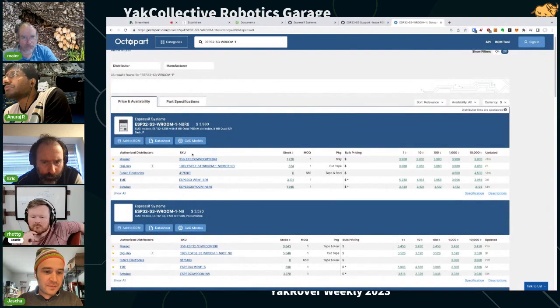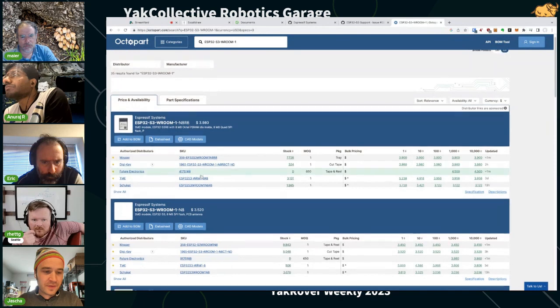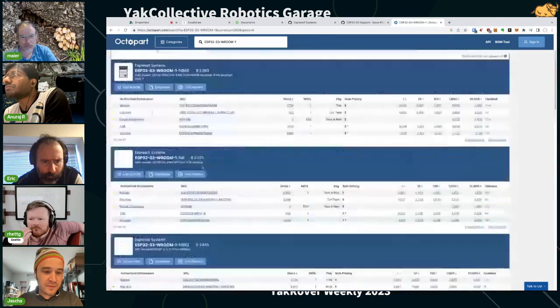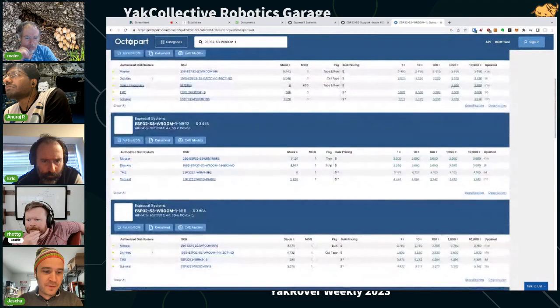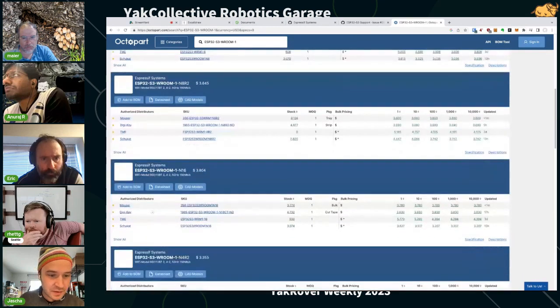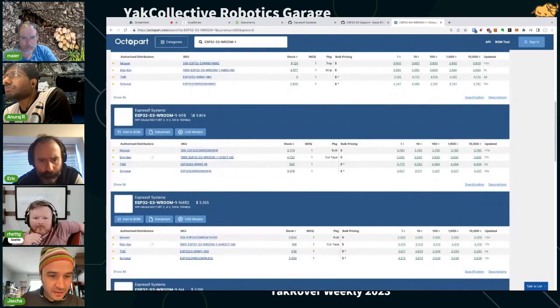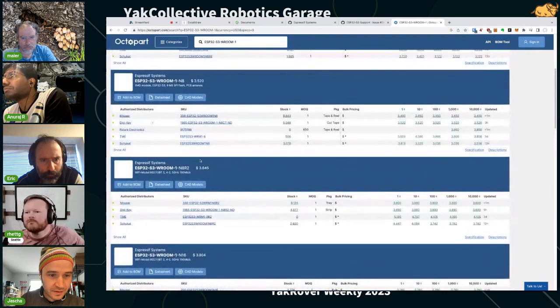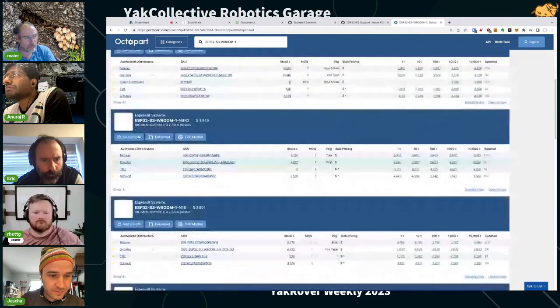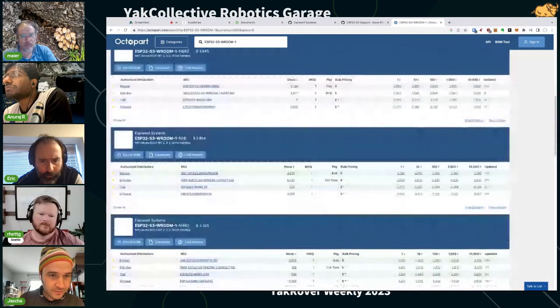You also have to keep in mind that these digits on the end, the N8, R8, refer to the amount of flash. Because, Eric, to your point, there are also different variants within the same module. The N refers to the amount of flash, and the R refers to the amount of RAM that they add as a separate chip inside the module.